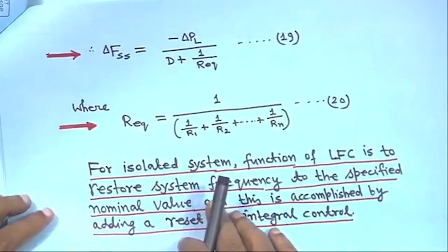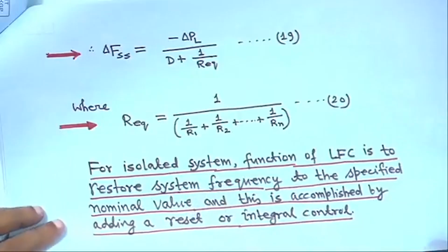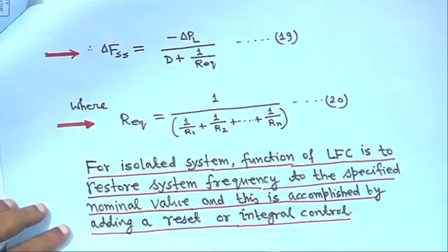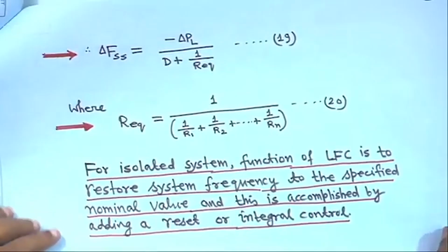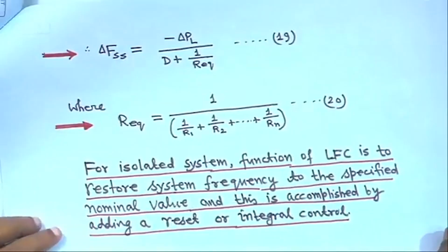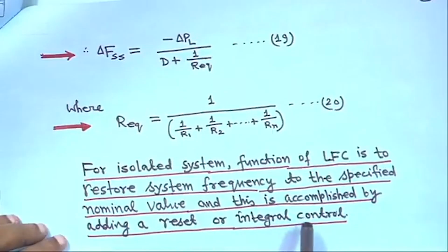Actually, for a thermal power plant, generally only integral control action is recommended, and proportional is also possible, but derivative control action for a thermal power plant generally is not recommended, right. The reasons are beyond the scope, otherwise we have to go into much detail, but for thermal power plants utilities generally prefer an integral controller having a very small gain setting. Reasons I will tell you later. But you have to go for integral control action, right.